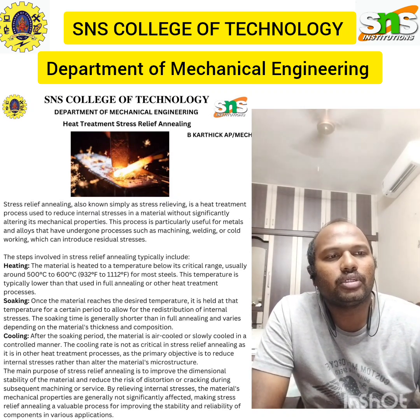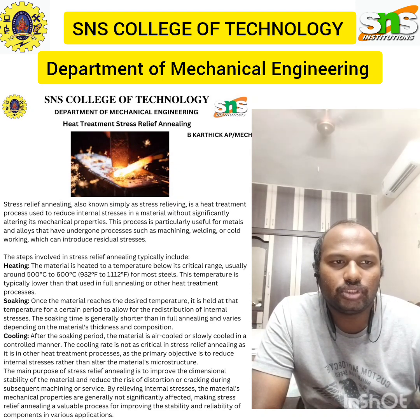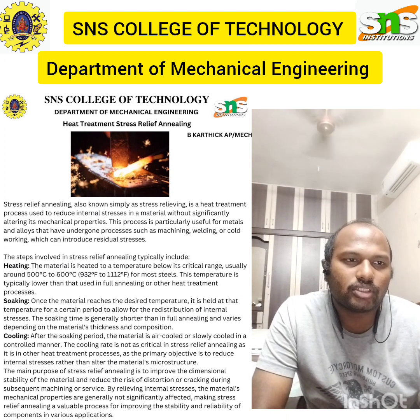The third one is cooling. After the soaking period, the material is slowly cooled down to room temperature. The cooling rate is typically not crucial for stress relief annealing, but can be relatively slow. The goal is to prevent the rapid reintroduction of stress